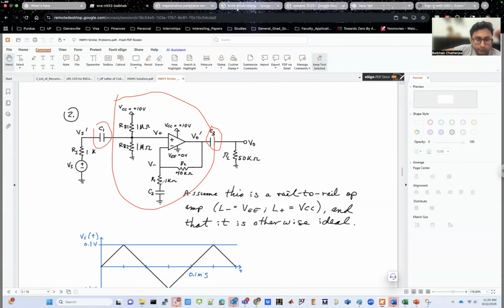All right. You have another capacitor over here, which is interesting at this point. And we'll actually discuss what kind of effect this capacitor has later on. But then, what you might say is that for AC, this capacitor is a short, which means that you have a shorted path to ground for any kind of AC signal. And that means you have this R2, which is 40 kilo ohm, divided by R1, which is 1 kilo ohm, as your gain, or basically the factor that determines the gain.